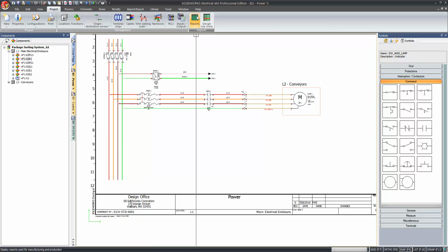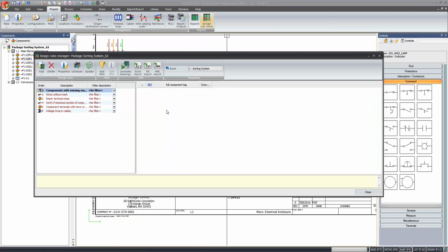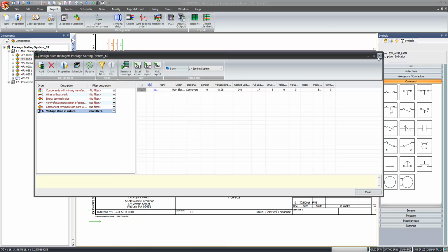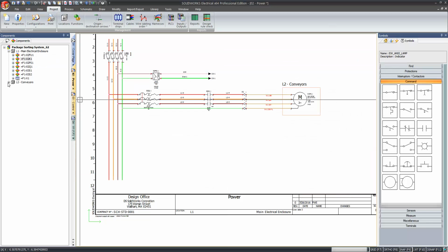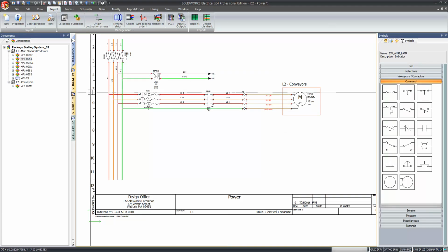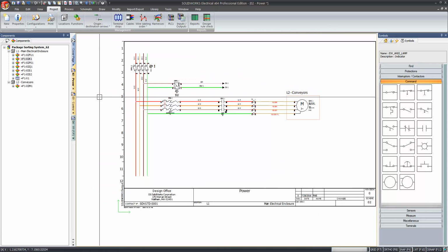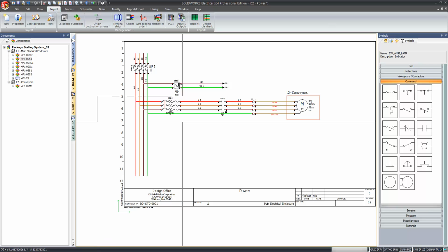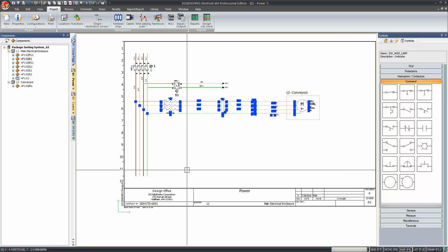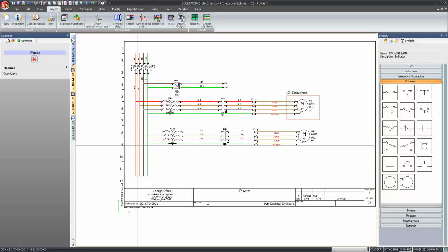And where that comes into play is in our design rule check. We now have a cable where we can calculate a voltage drop. All we need to do is assign it a length. And the reason I did that now is because that characteristic of having the calculation used will carry through when I copy and paste and use this in a macro. So there's copy and there's paste.